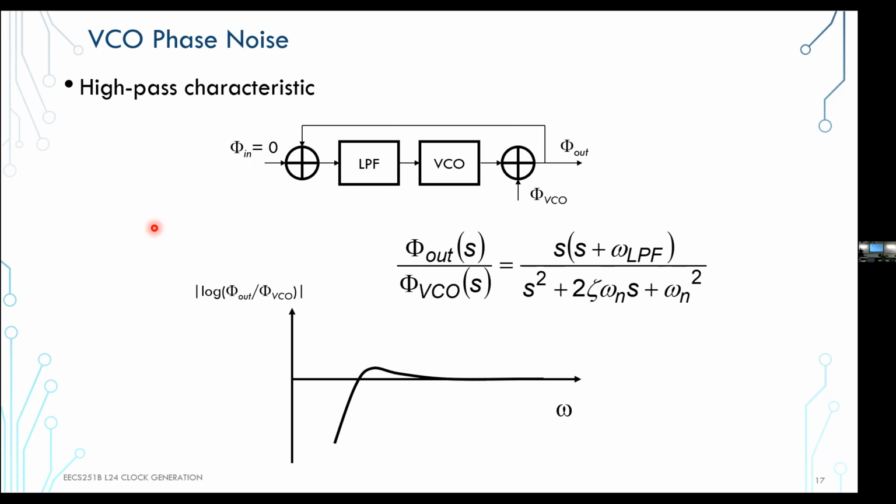And there's a little sweet spot there, which usually people use, knowing what their input clock is, knowing what their supply noise situation is, what type of regulation of the VCO they have. You can figure out in models where the sweet spot is in the PLL band, and set it there. I'm mentioning the input clock because you feed the input clock from the crystal outside. It has certain properties, but you also need to buffer it on chip. There you also add noise, right?